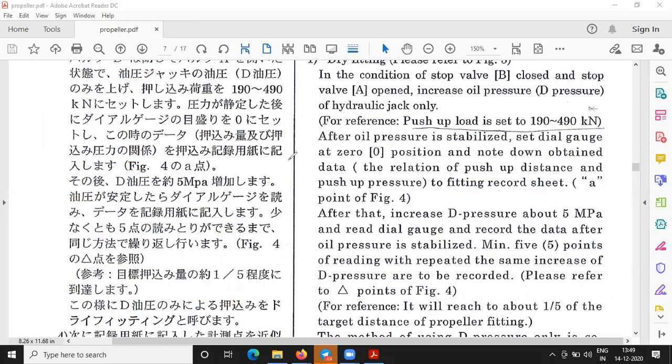Okay, let's take a normal spool and piston. A piston here, and here there is hydraulic oil. It is open-ended. When you push it, here there is a pressure gauge. Will the pressure gauge show any deflection? No. Okay, I will make this a little bit narrow. Will the pressure gauge show deflection? Yes. It will first increase, and then as long as the oil or water is flushing out through the hole, the pressure gauge will again drop.